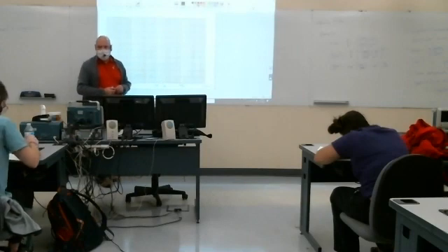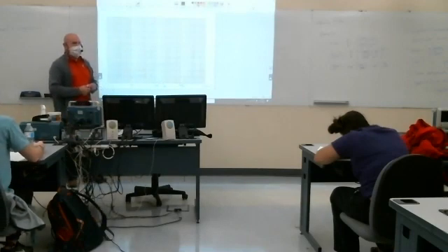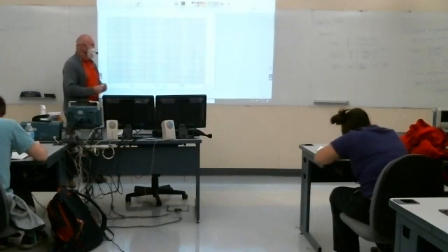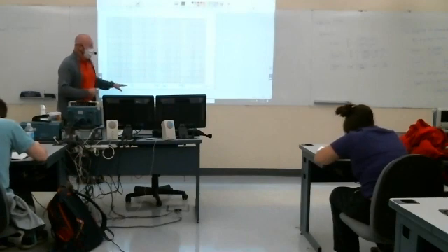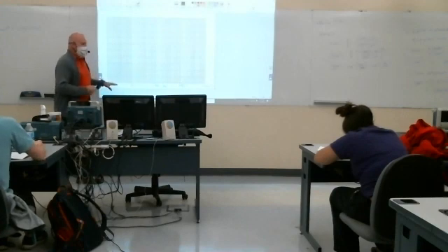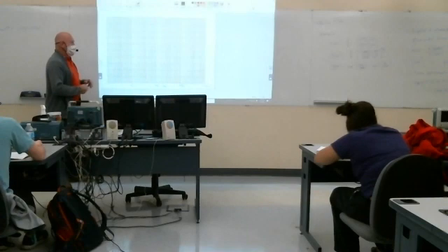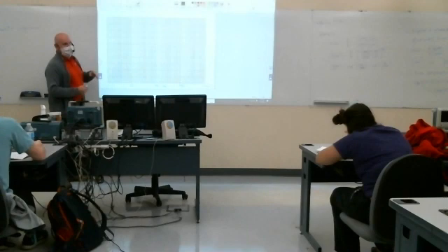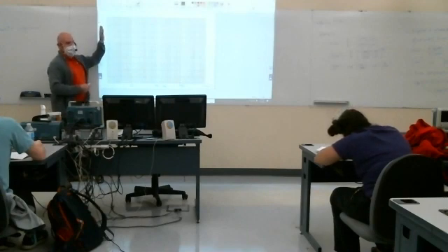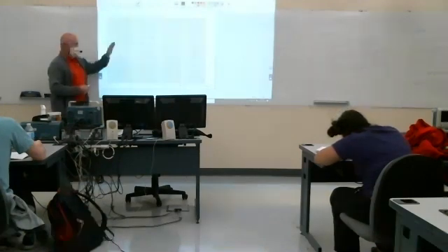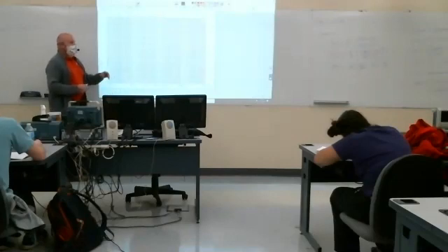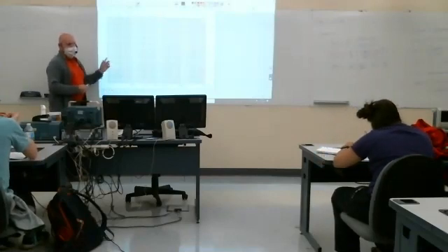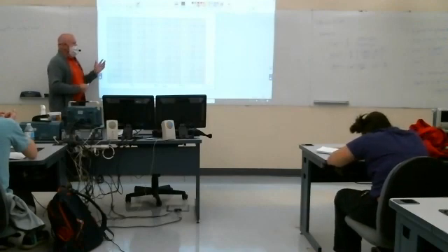Okay, everyone gets how this is laid out? It's a little bit unusual on that horizontal axis. So this is called semilog X. The x-axis is laid out in a log scale. It's called semilog X because the y-axis is a standard linear scale. So you can get paper that's semilog Y, where the y-axis is logarithmic and the x-axis is normal. Or you can get log-log paper, where they're both laid out logarithmically. For our Bode plots, we want semilog X.